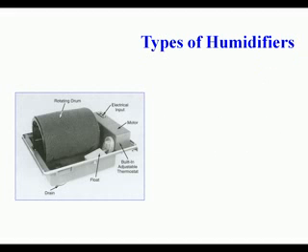Humidifiers use a vibrating object sometimes to atomize the water. The vibrating object can be a crystal that operates at a high frequency of about 100 kilohertz. That's 100,000 cycles per second. The unit produces moist air that feels cool on contact. Partially evaporated droplets are vaporized on contact with warmer objects such as skin.